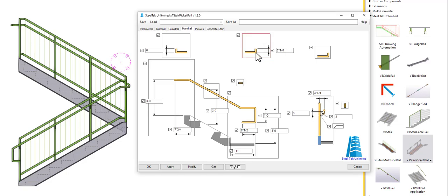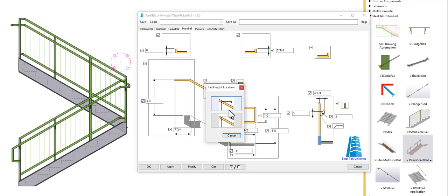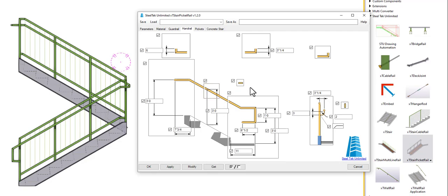Again, like on the top rail, you can set it to go to the top of the handrail, your height dimensions, or to the center line of the handrail. And we have several bracket settings: the radius, the offset from the center of the post, and the height of the bracket. And then the end of the loops, top and bottom, go from the top and bottom nosings respectively instead of from the stringers. You can set your height on the top, height on the bottom, and height on the sloping like you can on the top rail. You can change the rotation of the handrail profile, and you can change the rotation of the bracket profile.